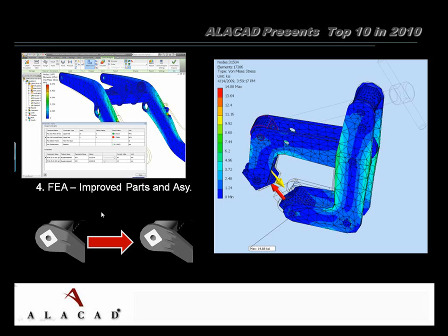Part analysis. Not only can it do single part analysis like it did before, but I can do parametric studies. This little rib here, I can determine through parametrics, okay, I need 1 rib, do I need 3 rib, and tell it I have 1 rib, here's the stress, go through and tell me what the least stress is. It tells me the least stress is with 3 ribs. I've quickly done a parametric study on this without having to run multiple iterations to try to find the best solution for my application. The software is helping me out, cutting down my design cycle, allowing me to improve my design.